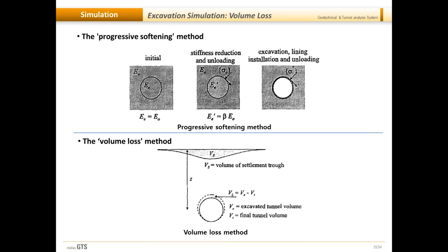And this is based on their predictive method, and this type of method can be applied only to soil strata where you can confidently and conservatively determine how much volume loss would occur for a given tunnel size. Usually it is given in some percentage of the tunnel volume, and engineers refer to different types of codes and practices recommended by FHWA to determine that for this type of soil strata this much volume loss would occur, so we should start with a certain amount of value.